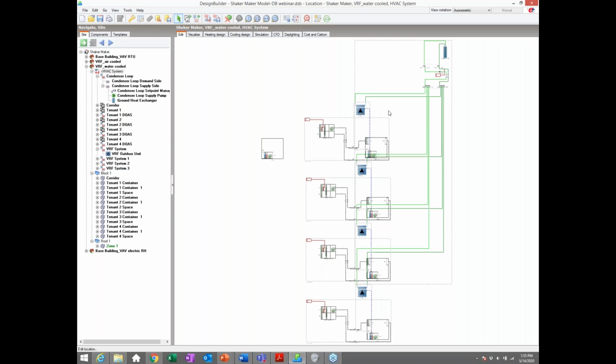Now in order to do that, you've got to decide how you're going to divide up these refrigeration circuits between your building. There are a number of ways to do that. Most common are either by occupancy profile. So in this example I'm showing here, we have 4 tenants that occupy 4 separate sections of the building. So they each get their own refrigeration circuit.